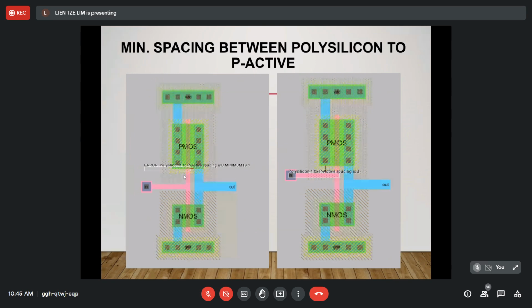When you do your practical later, when you start to design your layout design for a component, you will see this as well. I mention it here because I want you to take note that you can know what is the minimum spacing required between the layers when you design the layout.